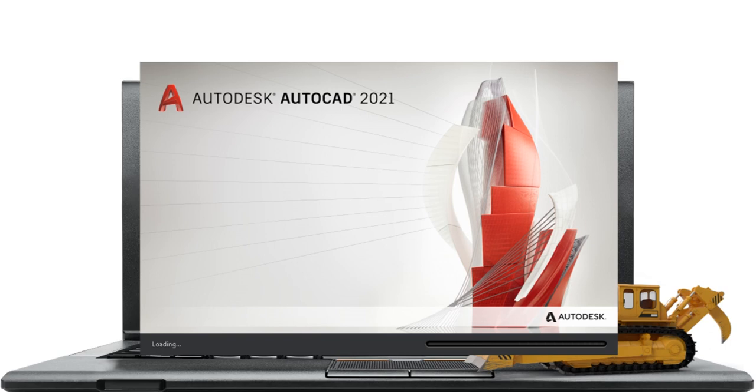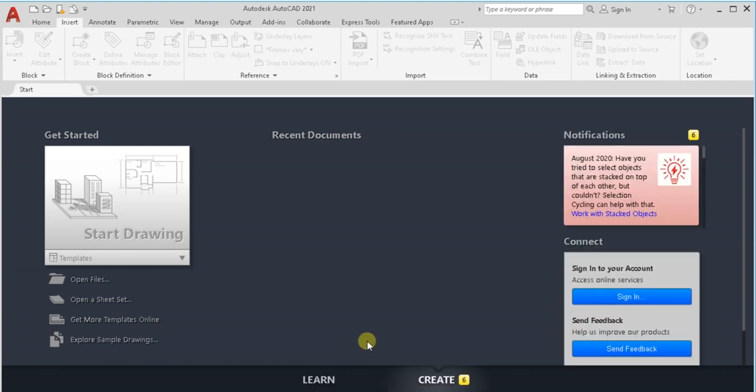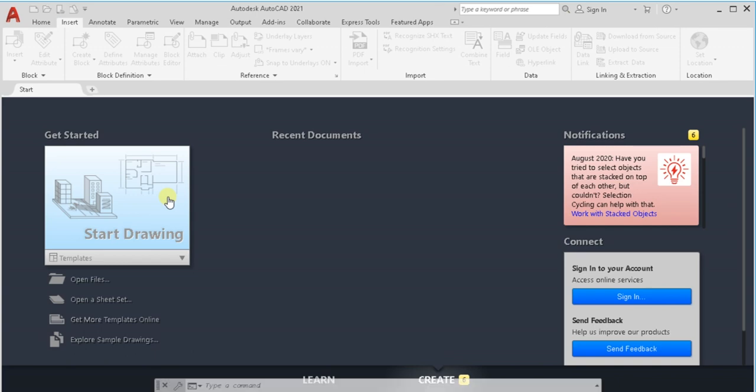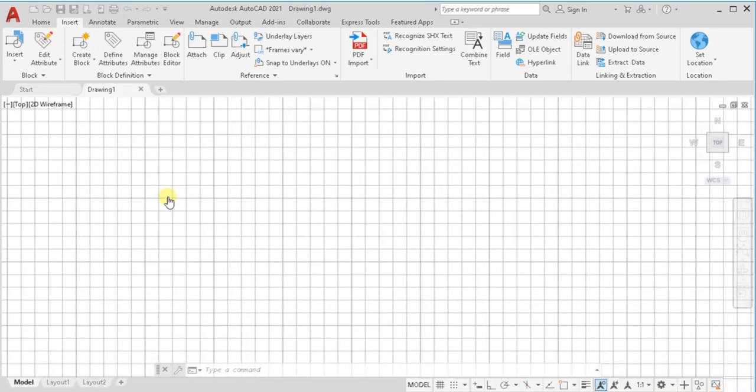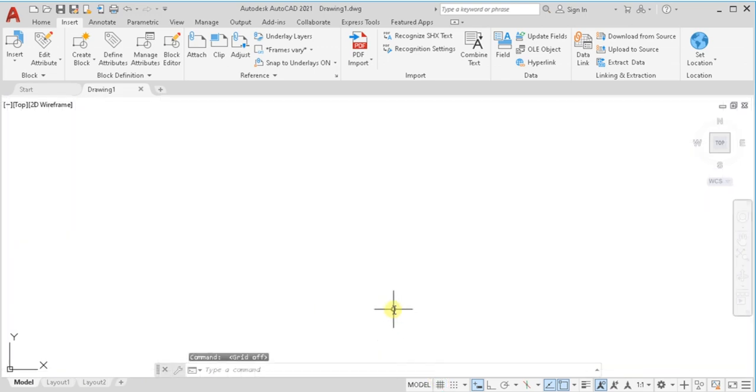Sometimes the user thinks why we have to create blocks. Instead, we can just place a copy of a specific geometry and paste it again and again wherever it is required. Yes, it is also a way, but a very unprofessional way. If we create a block, we can save it in a directory, and then if we are working in the same drawing, we can easily import that specific block anywhere, at any scale, and at any rotational angles.